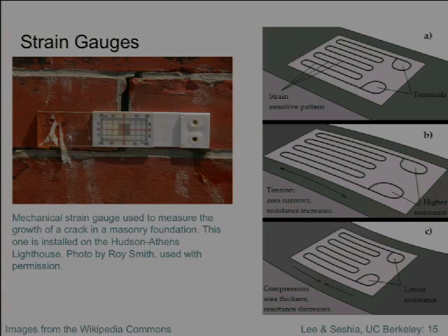So you can use that to measure even very, very slowly changing stresses. So geophysicists use this, for example, to try to predict earthquakes. They put in strain gauges strategically placed along a fault to try to detect very small movements in the fault and use them to measure increases in the strain on the rocks below.